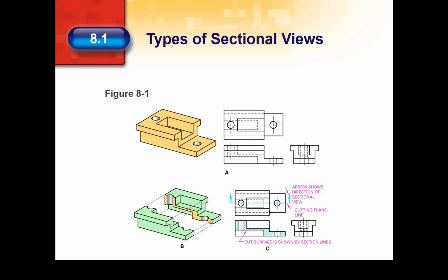On the sectional view, the cut surface is marked with thin, evenly spaced lines known as section lining or cross-hatching. The basic section lining pattern that uses thin, evenly spaced lines is used in most cases. It is a general-purpose symbol used for objects made of any material. It can be used especially when only one kind of material needs to be shown, such as on a drawing of a single part.